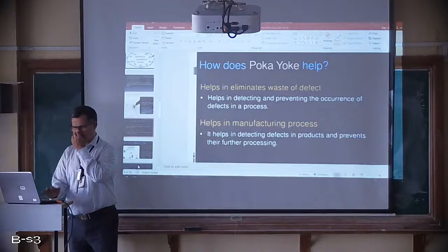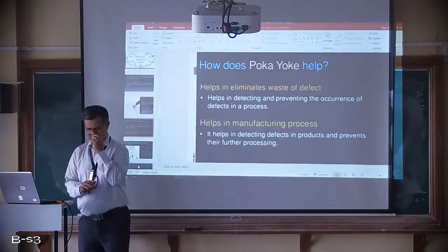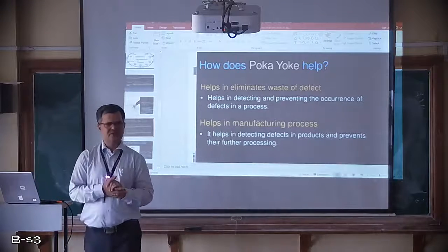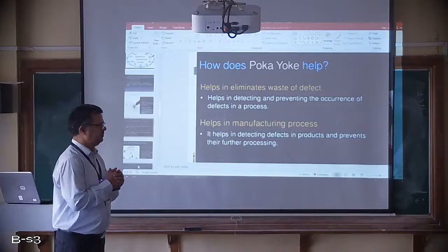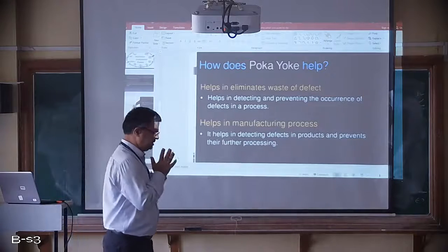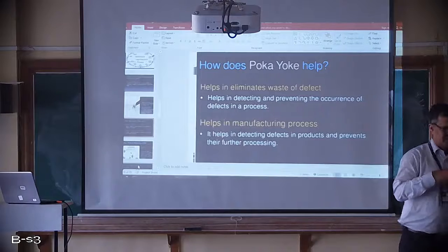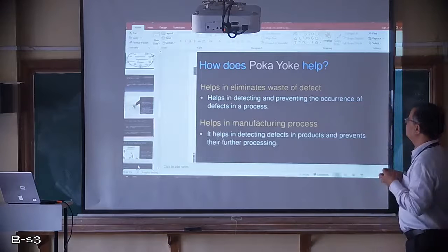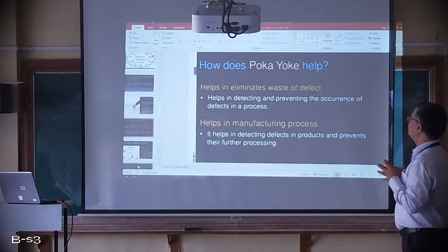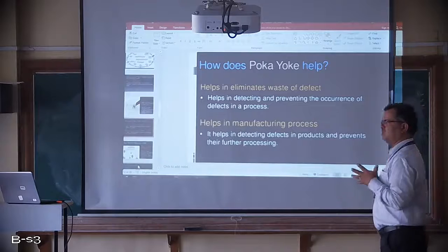Okay, how does Poka-yoke help? In lean, Poka-yoke is one of the lean tools. How does it help in improving the performance of the organization or the productivity of the system? It helps in eliminating the waste of defects. Remember, defect is one of the wastes.